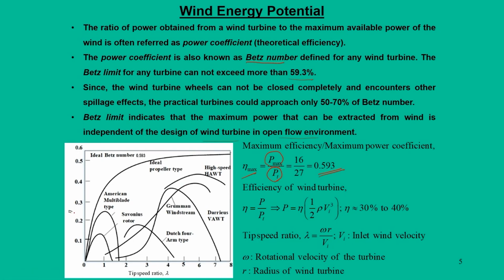So, that way one can plot the power coefficients as a function of tip speed ratio. But what happens here is that when you install a particular turbine at a given location, it depends on three major factors. One is the maximum swept area or capture area that we can achieve. That is achieved through the rotor area or wind turbine area, which is defined by its radius r, and the omega, which represents, with a given wind speed velocity V, the rotation of the turbine that we can achieve, that is the angular velocity.